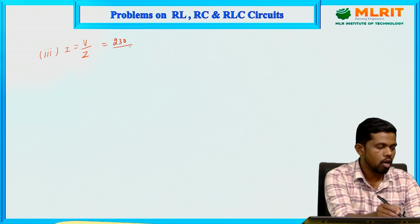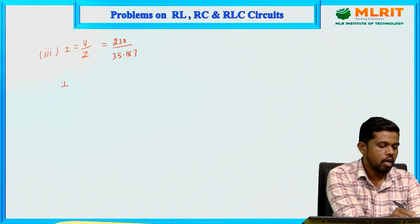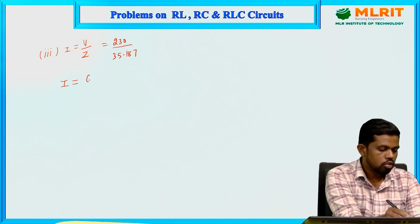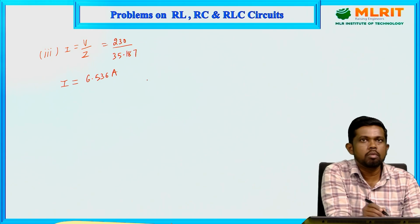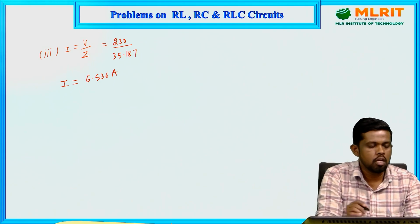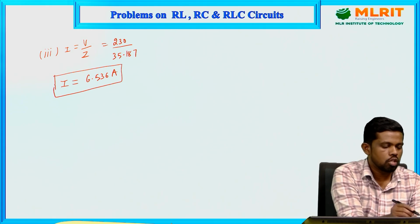The Z value we got is 35.187. Therefore the current flowing through the RC series circuit should be 6.536 ampere. So the ratio of 230 volts to the 35.187 impedance of this network gives 6.53 ampere current flow. So this is question number 3.